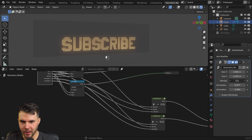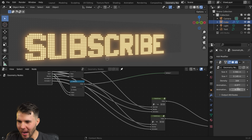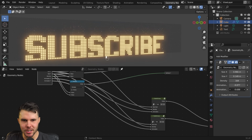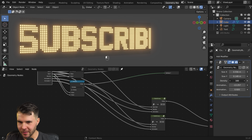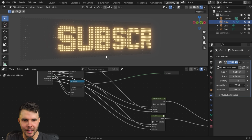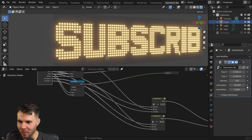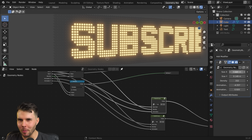And this is great. Now, there is one little problem here, and it's something that only happens once you go beneath the value of 1 for the X. It doesn't quite line up anymore, and you might notice it more on the Y, but you might see some stuttering. Maybe I have to go to a lower density. I can't remember how it is that I see it, but you'll see it on a couple of letters. Oh, there we go. Just on the U there. You can see that U was 4 pixels wide, and now it's become 3. So something's happened there, and it only happens once you go below 1.